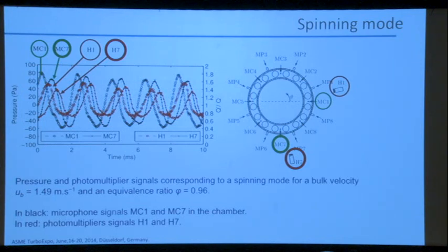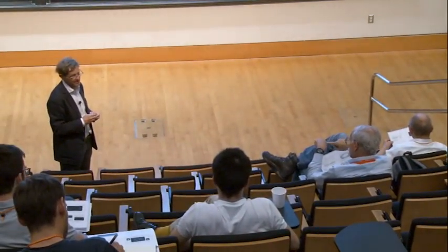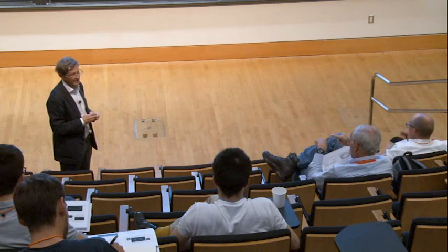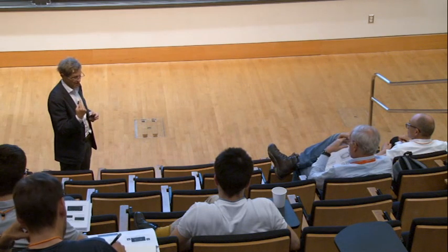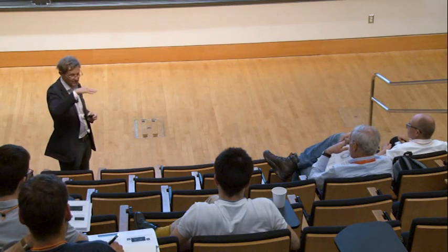In a combustion engine, you use a strobe light to make the shaft appear to stand still. If you were to feed a swirl frequency into a strobe light, would you be able to see the individual flames in the swirling flame? Using stroboscopy. Yeah, stroboscopy with Schlieren. If you make Schlieren and use stroboscopy, you can actually see the motion.